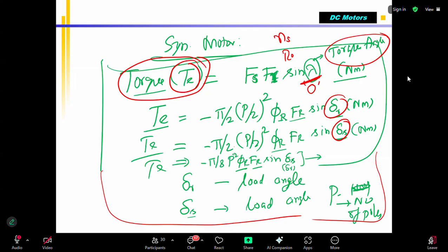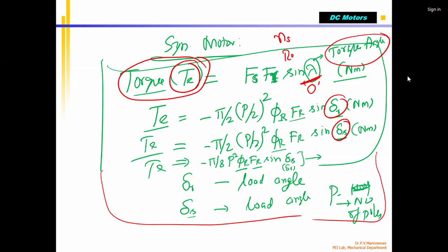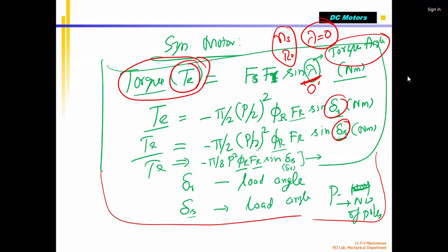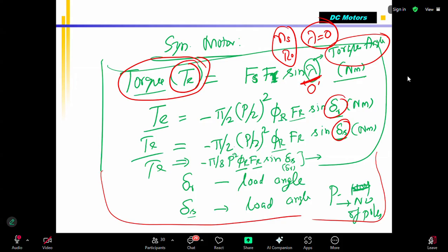But even once it catches, when you remove the starting motor, because the rotor has mass, it will lag and the speed will reduce a little bit. So this will never become zero. If it did, the motor would not be able to produce torque. The rotor mass itself acts as a load in no load condition. In actual load condition, lambda will become more and more, and lambda divided by 2 gives the load angle, correct? Thank you for asking the question.